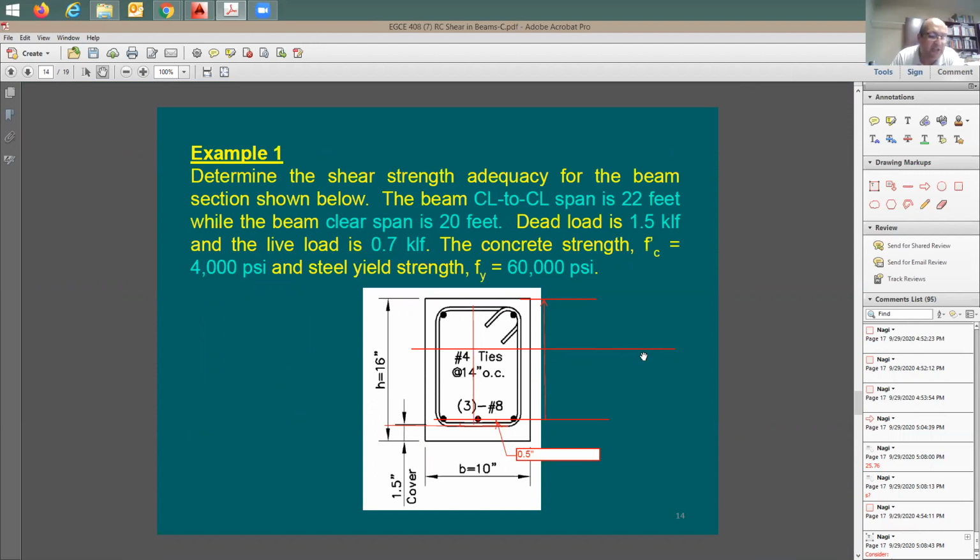I would change the spacing. Because in a large scale, probably if you reduce, for example, 2 inches, maybe in 100 feet, the number of ties we use, set of ties we use, maybe is more than if you just add one another tie in between. Are you going to be adding this one tie for 100 feet? I'm just assuming that if yes, no, I'm just asking. Are you going to be adding it at 100 feet? Yeah, for example. It totally depends on what the scale we are working on.